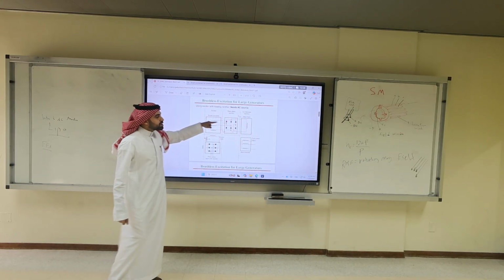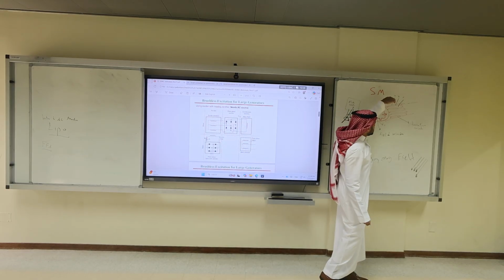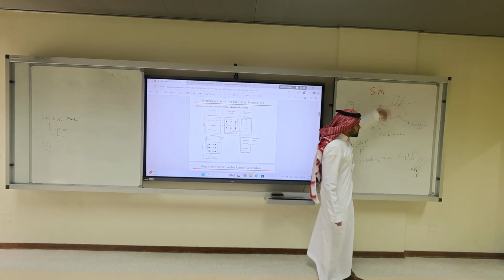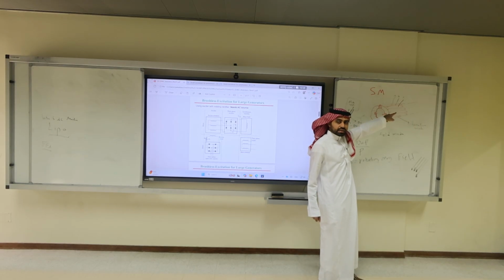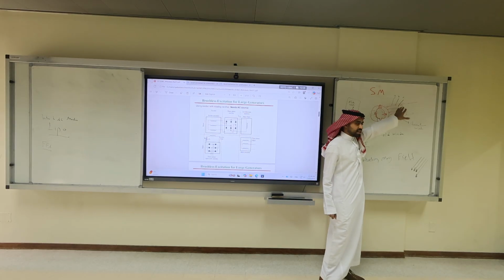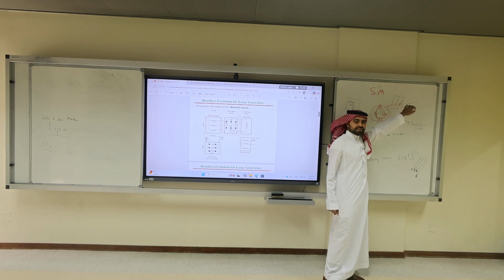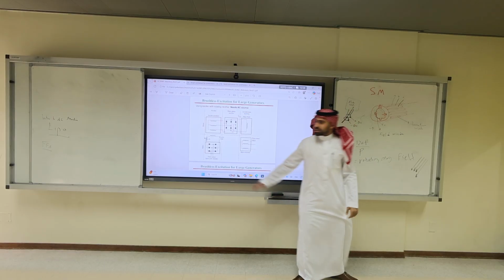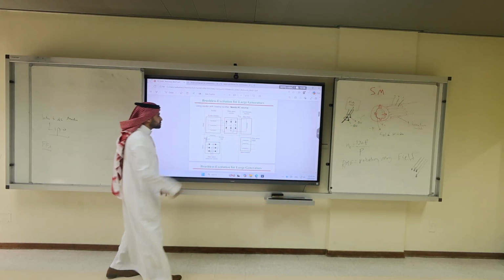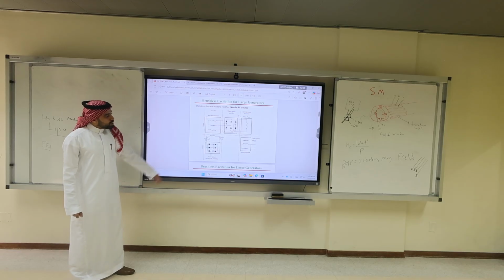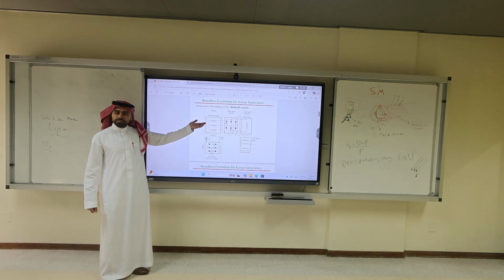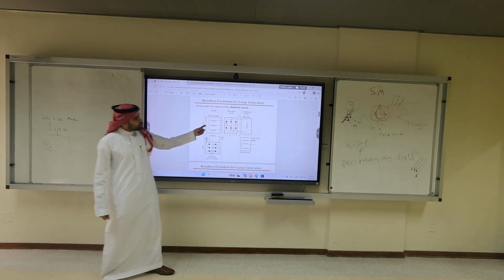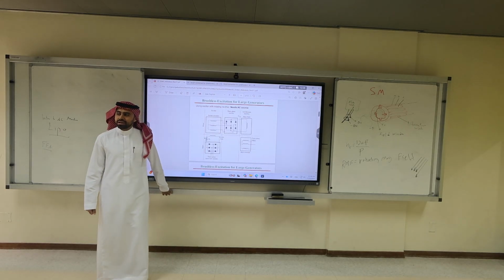Then the rotor windings, we will start spinning them. The rotor windings are cutting the constant flux lines from the DC from the stator. I know ultimately it's an AC machine, but we're applying DC at the stator. When we move the rotor, it cuts the constant flux lines, so we're going to have an induced voltage in the rotor. That induced AC voltage from the rotation is connected to another three-phase rectifier, to get it to DC.